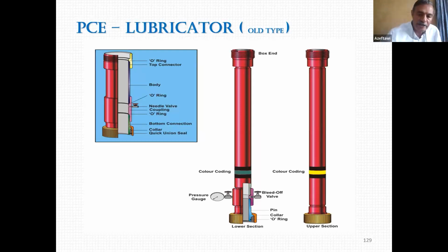If you look at the cross-sectional area, this is what you see here. This piece is connected to that piece, this piece is connected to that piece, and this piece is connected to that piece. Internally, we have an O-ring to make the seal for every connection we make. This is rubbish because nowadays it has to be integral, which means one piece.